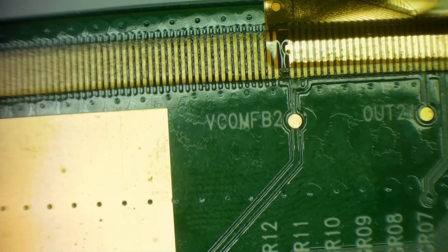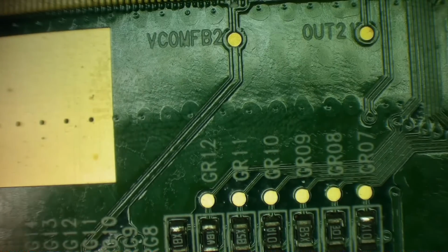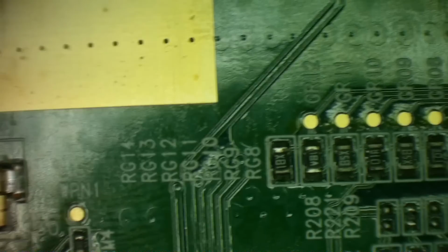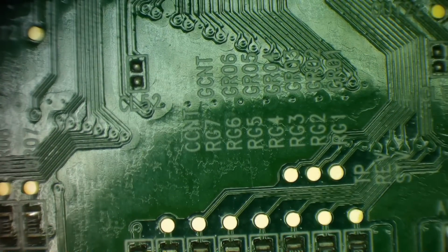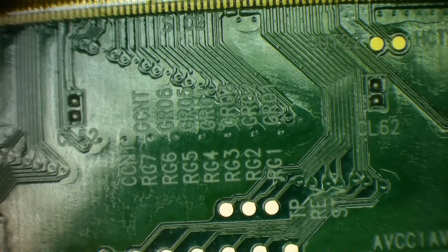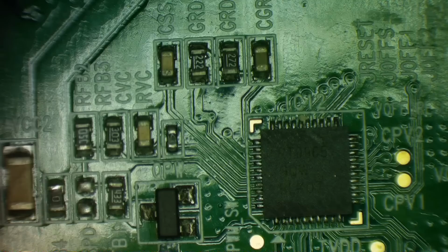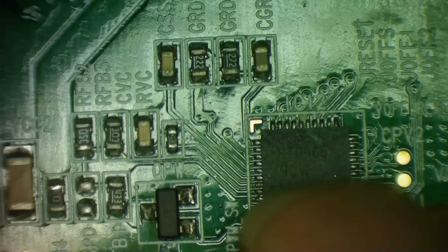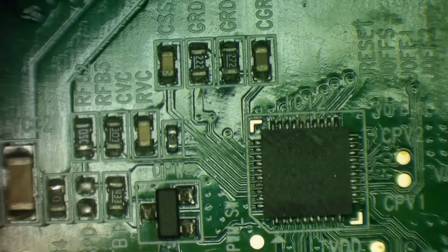And then I bet these are gamma as well. Yeah. GG, RG, I'm not sure about those. RG sounds like red and green, but I don't think that's it. I'm sure this is to do with gamma voltages. Okay. So I suspect that the problem isn't here, and although these chips could give you no image, I don't think that's the case here. But anyway, let's see what it is.